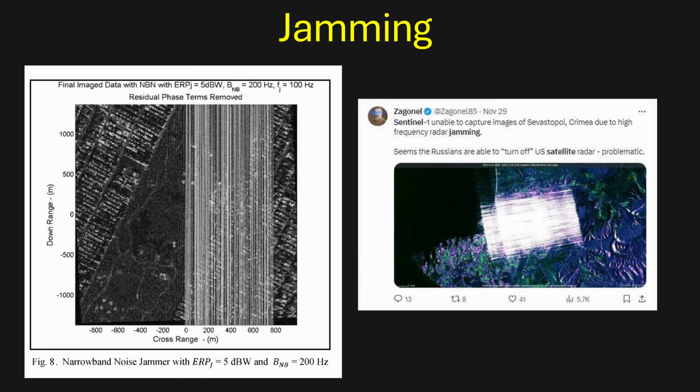There are lots of types of SAR jamming, and what you see here are different types of noise jamming. You could do wideband, which just decreases the signal-to-noise ratio, or you can do narrowband like you see on the left there. You can also send out modified chirps that match the radar, which can produce false targets and even false scenes or giant clouds of targets.